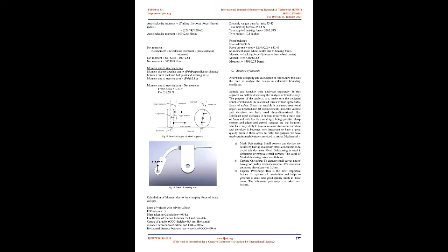Firstly, the suspension hardpoints along with the wheel center point and outer track rod ball joint were plotted with their respective coordinates in a space of SolidWorks. The next step was to locate the distance of the brake caliper mounting from the wheel center, which depends on the positions of the hub and brake rotor and also on the distance between both the holes of the brake caliper.